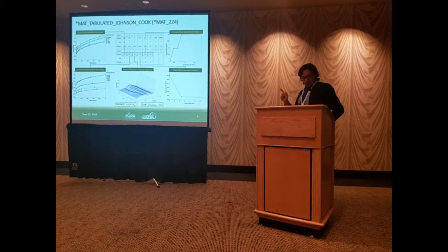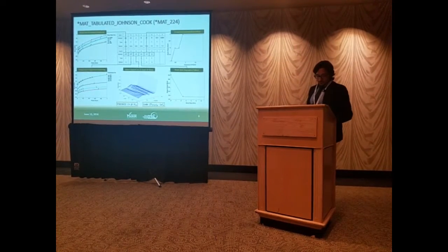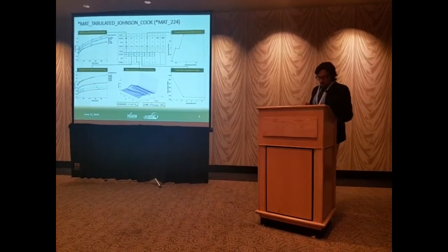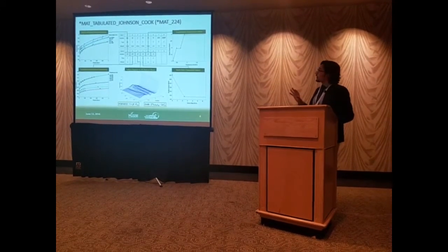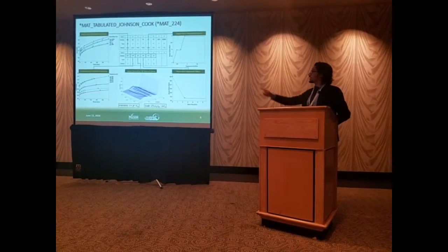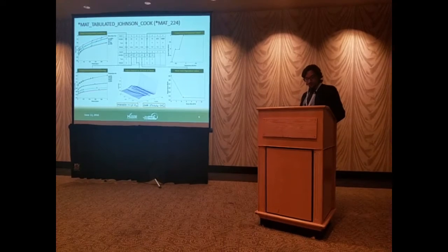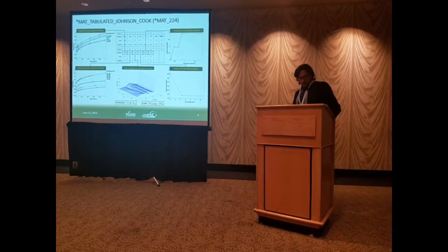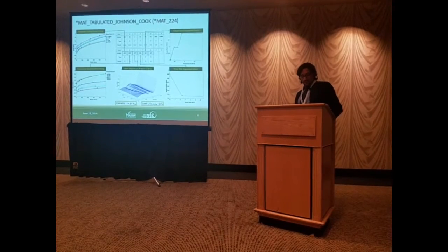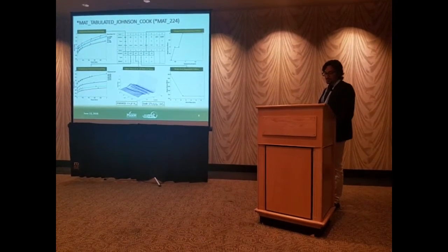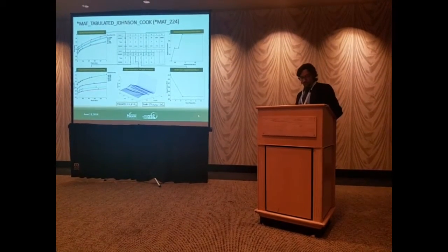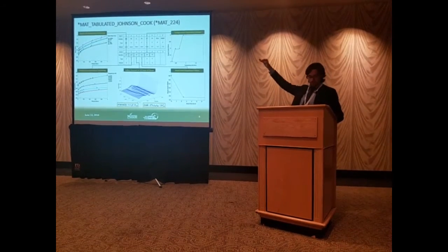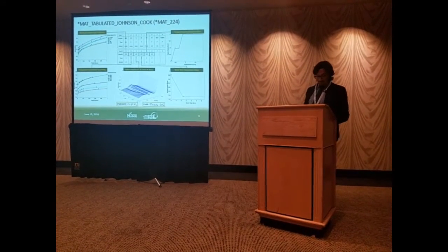So, this one is the MAT224 input deck. I want to show you just some key points. Starting on the left, we have LCK1, the strain rate sensitive table. It defines effective stress as a function of effective plastic strain for each rate.